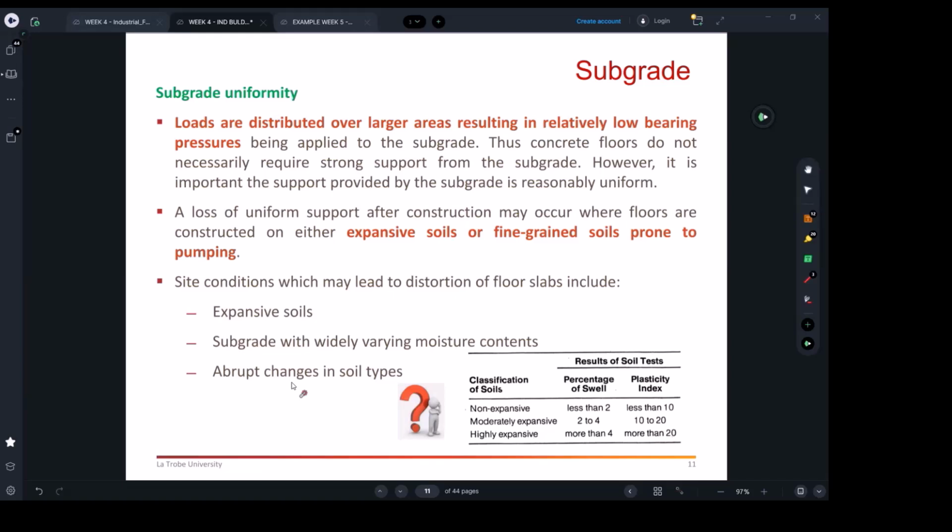You have sites where you've got 0.5 meter of fill, which is just deposited material. Then another part is going to be basalt, then another part may be clay, so again, the soil report will tell you all these things. It's not your job to make a design, but you need to know about it because you're going to build it. So don't think the engineer will do all what they have to do to design a proper slab. The soil engineer will do whatever they do to excavate the soil and make tests, but you need to know how much it's going to cost you and the limitations of construction. So that's basically what you need to do.